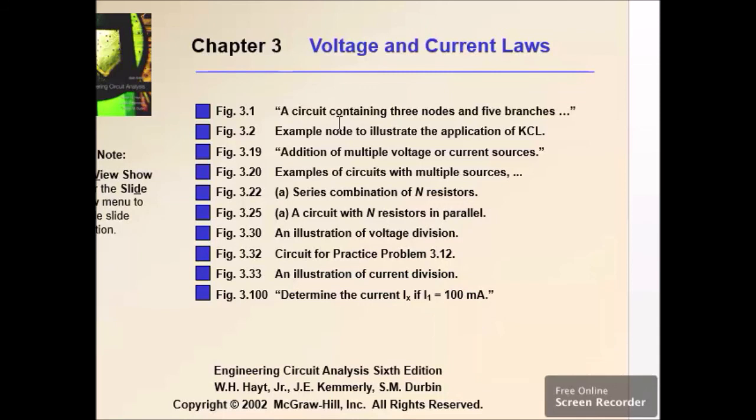Okay? Kinumbine din natin yung mga series resistor. Kapag naka-series resistor, edi i-add mo lang. Kapag naka-parallel yung mga resistor, meron tayong formula. Yung pinaka-formula is 1 over R equivalent is equal to 1 over R1 plus 1 over R2 plus 1 over R3. Kapag dalawa lang yung resistor, special case: that is just the product over the sum, so R1 times R2 over R1 plus R2.